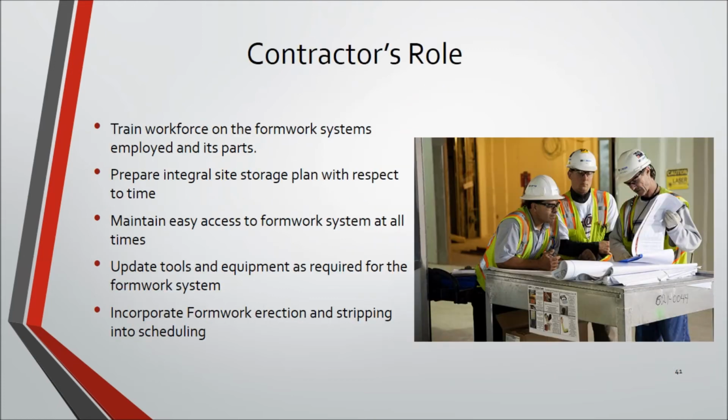The role of the contractor is to train his workforce to handle the formwork system. He must prepare integral site storage plan or even a 4D storage plan. His aim should be to maintain easy access to the formwork system at all times and ensure worker safety. He must also ensure to be technologically up to date. It shall be wise to incorporate the various stages of formwork erection and stripping into the construction schedule to reduce clashes. So these are the key advices for these professionals. If you belong to any of these professions, kindly keep these in mind and avoid overruns by maintaining high formwork productivity.